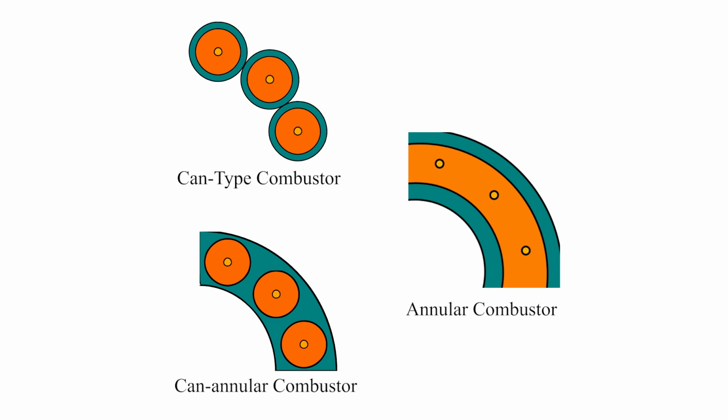Carbon dioxide is a product of the combustion process, and it is primarily mitigated by reducing fuel usage. On average, 1 kilogram of jet fuel burned produces 3.2 kilograms of CO2. Carbon dioxide emissions will continue to drop as manufacturers improve the overall efficiency of gas turbine engines. Unburned hydrocarbon, or UHC, and carbon monoxide, or CO, emissions are highly related. UHCs are essentially fuel that was not completely combusted. They are mostly produced at low power levels where the engine is not burning all the fuel.